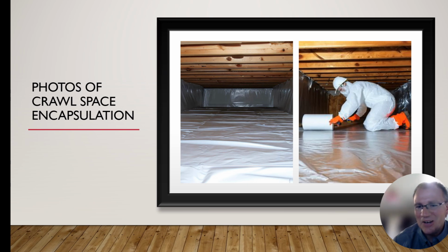One thing that I did notice on this job, there was no gap at the top of the block foundation to do termite inspections in the future. So looking at it from a pest and termite control point of view, you definitely are going to want to leave a 4-inch gap on the block up at the top to make sure that you can do termite inspections in the future.